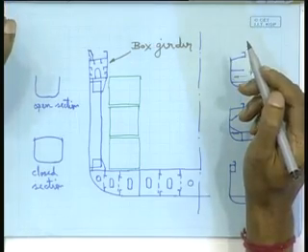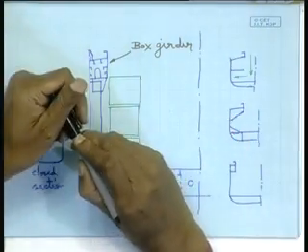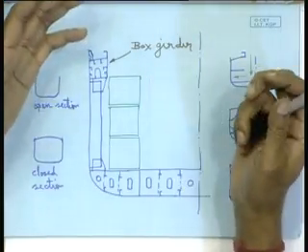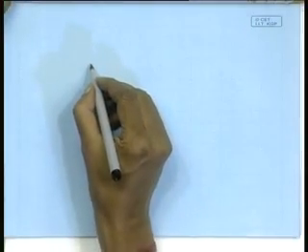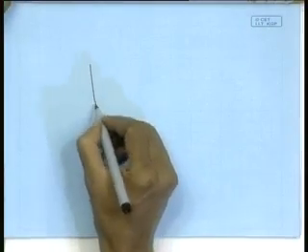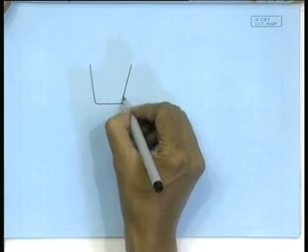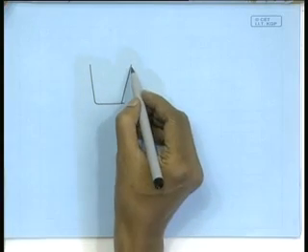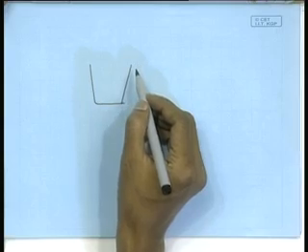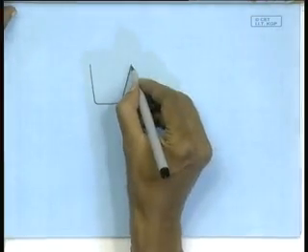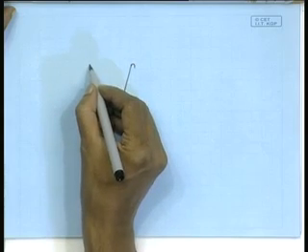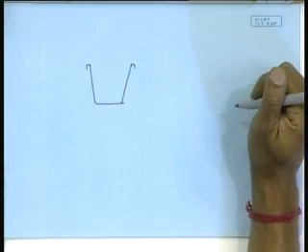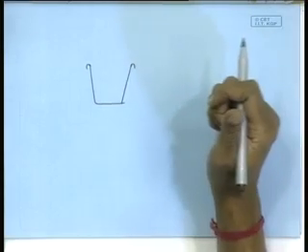It is something like you have observed, for domestic use, the tumblers I was talking about. What you see in tumbler, just to give it the necessary torsional strength, right? They are generally of this shape, right? If I keep the edges without any stiffening, it does not have any torsional stiffness. Just to provide stiffening, this is bent like this, isn't it? Those plastic tumblers, domestic tumblers, that gives you the strength.